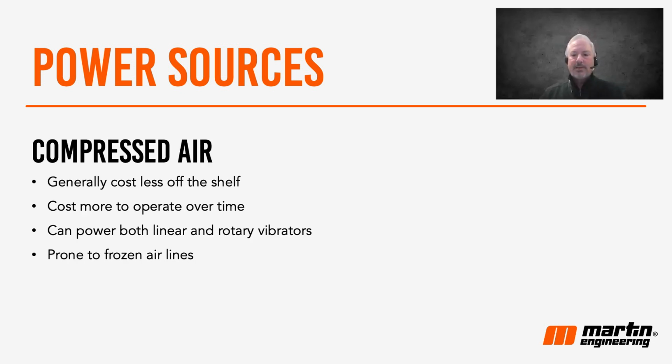When we're looking at compressed air, there are some issues with them, but there's also some real virtue to them. They cost less off the shelf compared to the electric vibrators, but they'll cost more to operate over time due to the power consumption of the air compressor that produces the compressed air to operate.